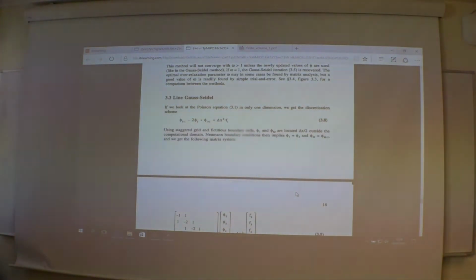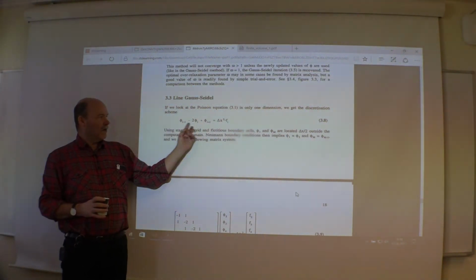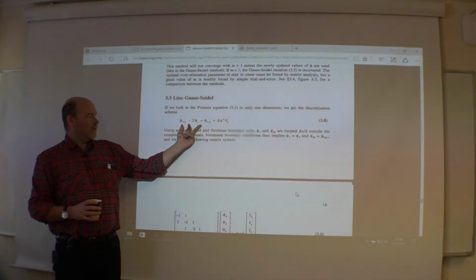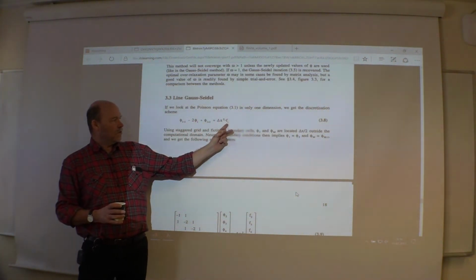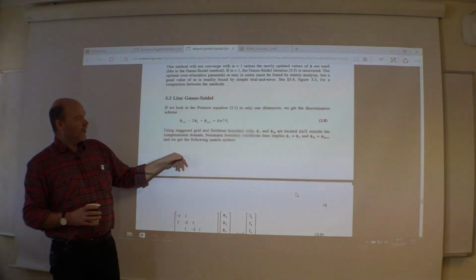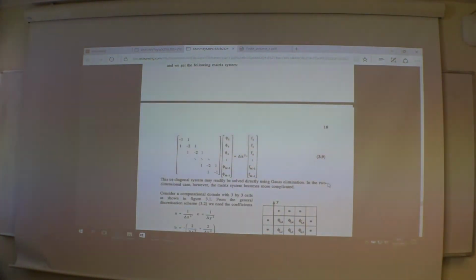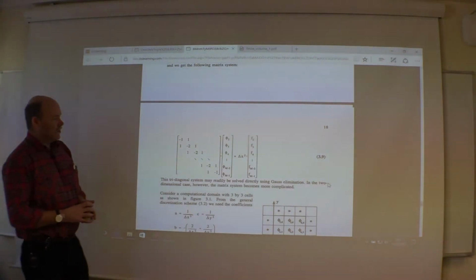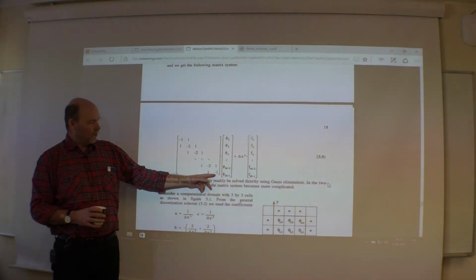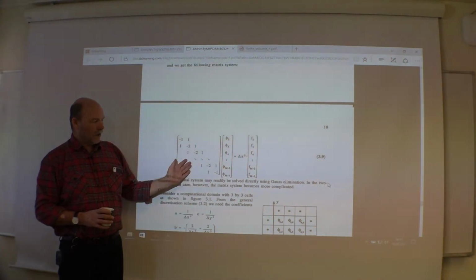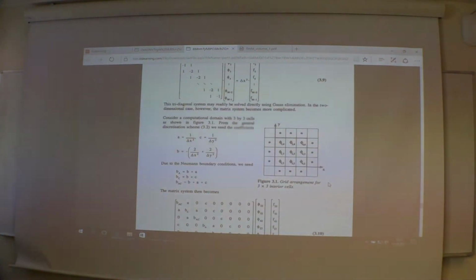The line solver, you just choose one line and say, these are now my unknown. And since it's a double derivative, you only have 3 unknowns equal now to the right-hand side. And here, inside here, you will have then the other neighbors that is missing in the other direction, of course. But you will end up with a 3-diagonal equation system like this. Diagonal will be -2, something with the boundaries, of course, and then another bond, which then can be solved using a direct method, like the Thomas algorithm. So no problem there.